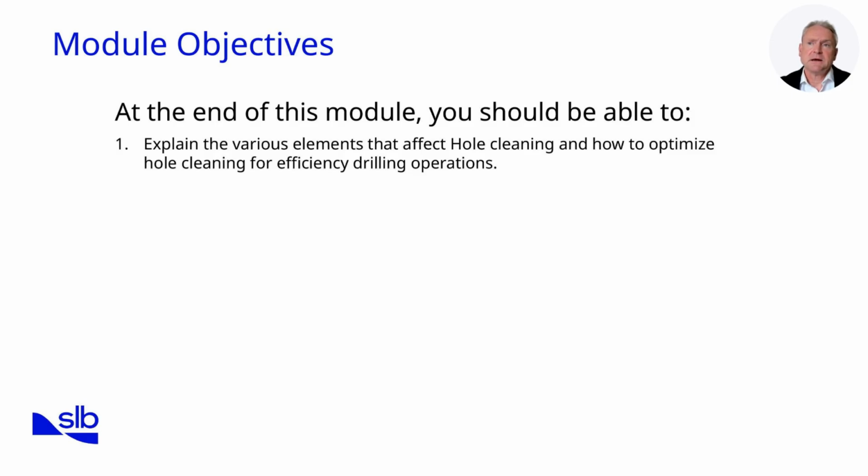Finally, we will consider optimization strategies such as adjusting annular velocity, maximizing hydraulic horsepower, and optimizing nozzle velocities. We will conclude with a design approach, looking at annular velocity and mud weight, tying all concepts together. By the end of this session, you will have both theoretical and practical insight into how to manage hole cleaning for efficient drilling operations.